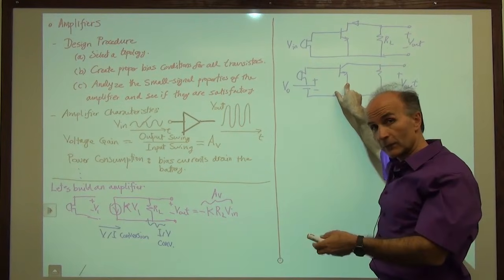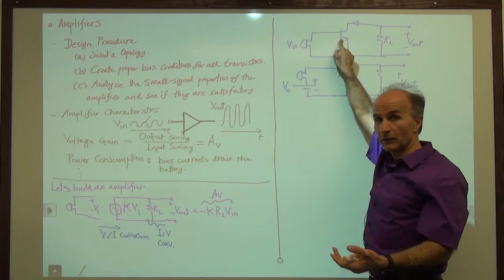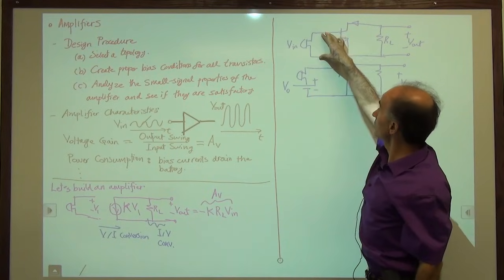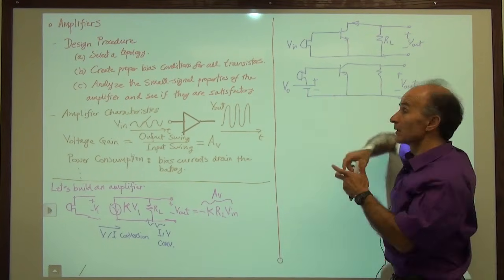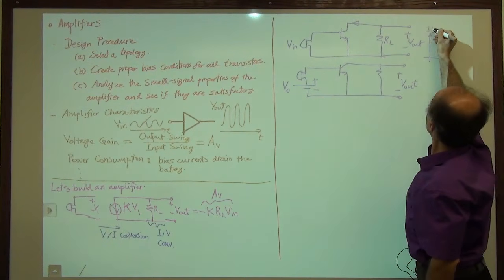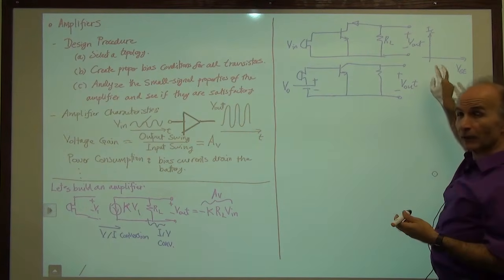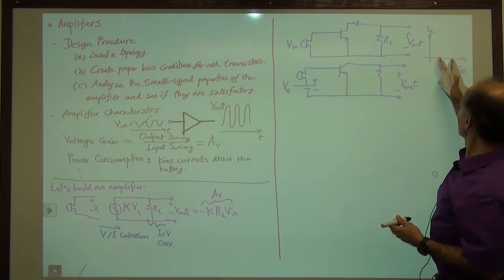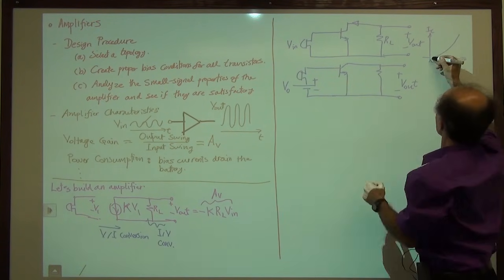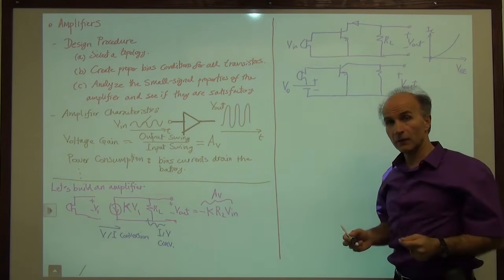Once we have a bias current, we have a certain GM. Here, the transconductance is 0, because the bias is 0. The transconductance tells us how well the bipolar device converts a voltage to a current, right? So here's what we have. IC versus VBE. How well the transistor converts a voltage to a current, a voltage change to a current change. So in the first circuit, we are here. So when the base emitter changes, the current change is extremely small, not very useful.